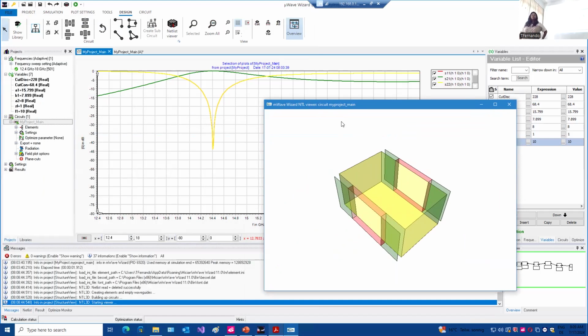Now at the frequency response, you see that S11 means you input something into port number 1 and do a measurement from the same port, meaning that you get a reflection, right? You send something, you measure from the same input, meaning you get reflection.